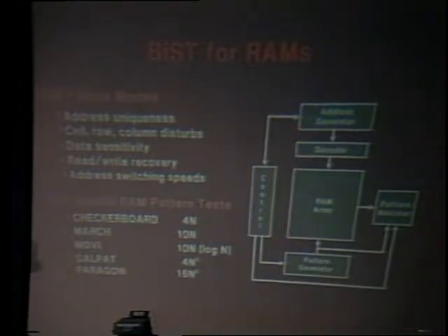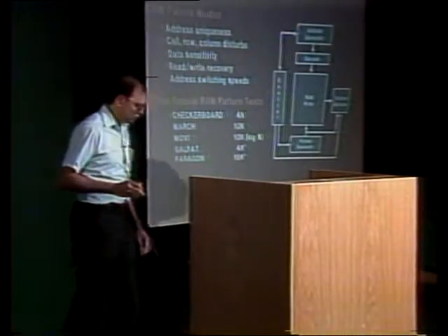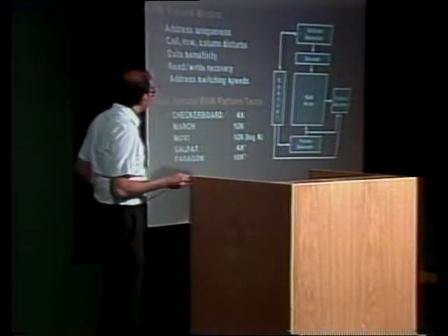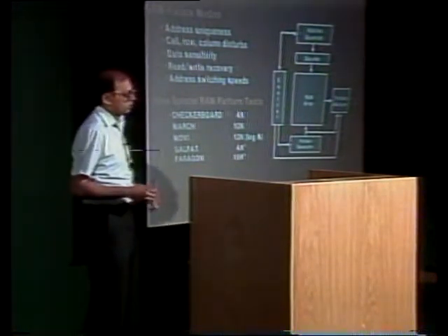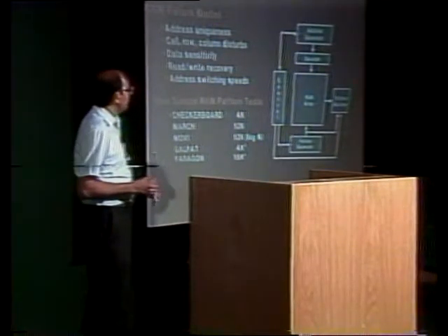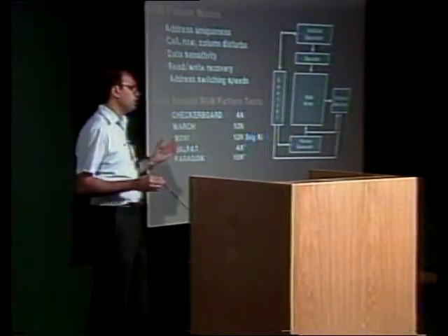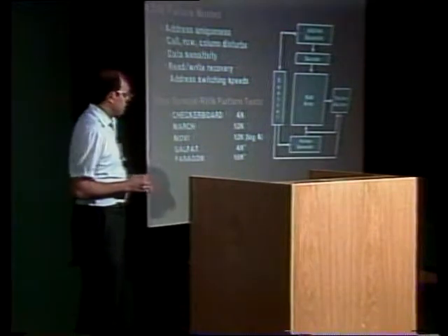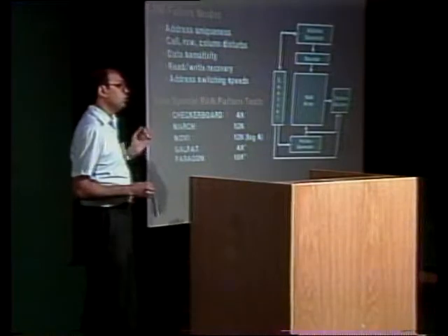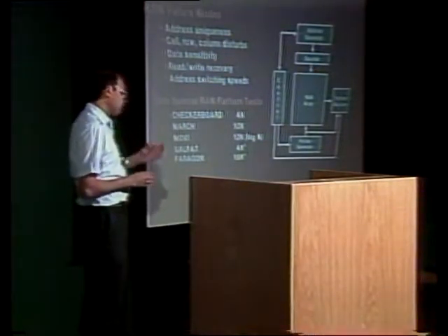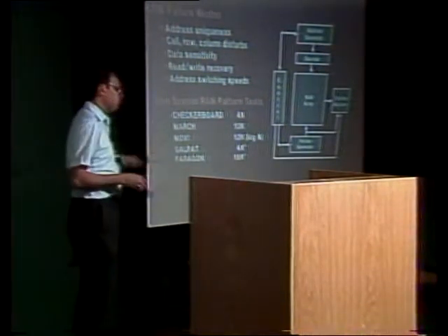Each one of these is designed to go after a specific set of failure modes listed here. Now we don't have time to go into the detail of those, but the trouble is all these tests run for too long, and your problem is compounded if the RAM is embedded in logic, and then it tends to chew up a lot of testing time. Plus, you may not have enough access to the memory when it is embedded to apply those patterns.